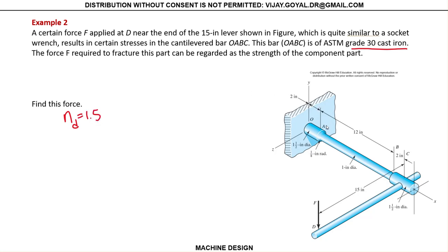And again, we are looking at this particular location. One thing you can see from this location is that your big D is 1.5, that's the big D here, and then the reduced d is 1.0. Your radius is 0.125 inches. This is given from the geometry itself, and we know those values. Now, for this to be safe, as before, we will have to make sure that this is bigger or equal than 1.